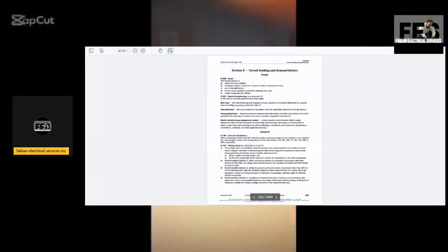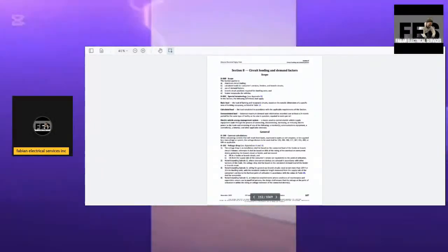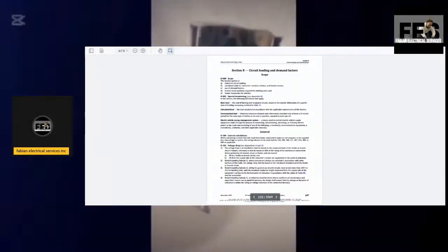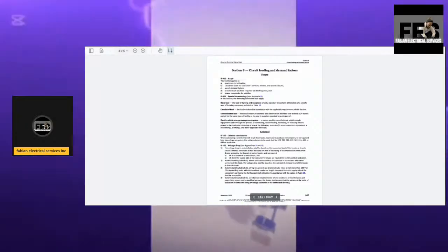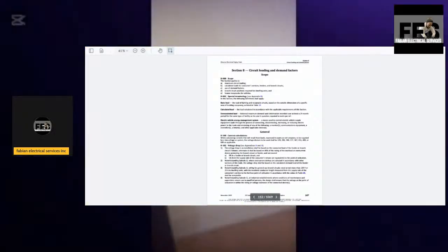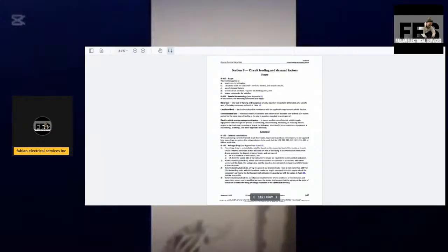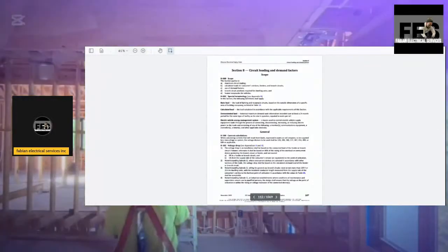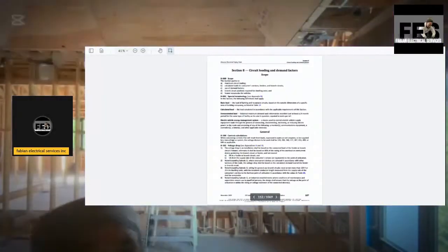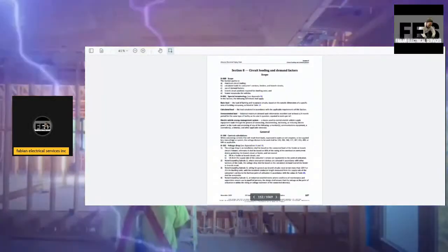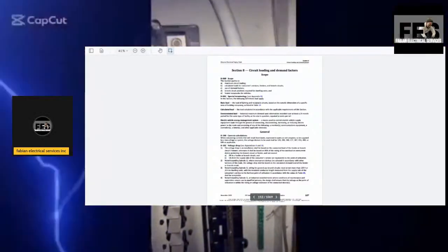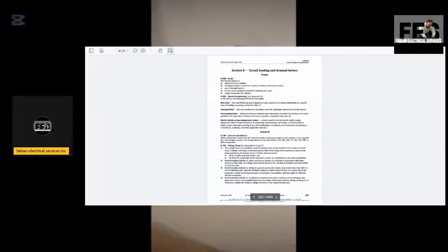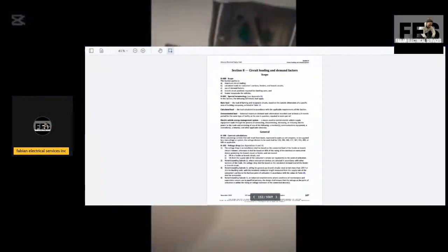Notwithstanding Subrule 1, where overcurrent devices are selected in accordance with other sections of this code, the voltage drop shall be based on the calculated demand load of the feeder or branch circuit. Notwithstanding Subrule 1, wiring for general use branch circuits rated at not more than 120 volts or 20 amps in a dwelling unit, with the insulated conductor length measured from the supply side of the consumer service to the furthest point of utilization in accordance with the values in Table 68, shall be acceptable.